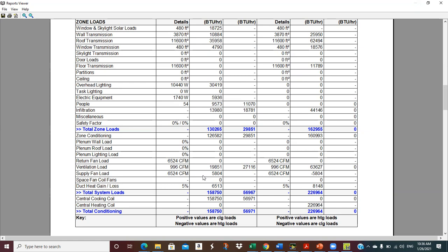Everybody out there and on the video recording, write down 12,000 BTUs per hour equals 1 ton of cooling. And that comes from the days when the ice truck used to run. So the ice truck used to run every 24 hours.